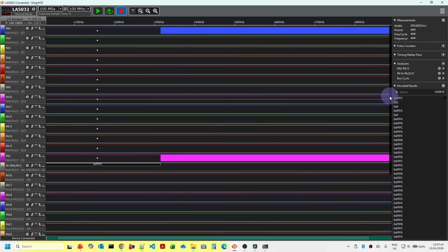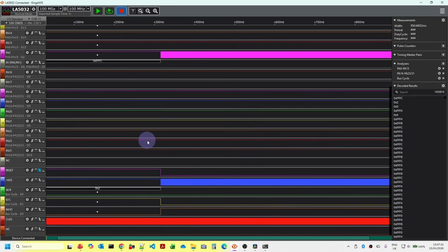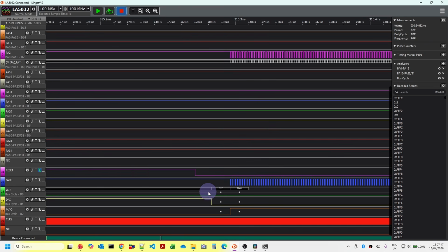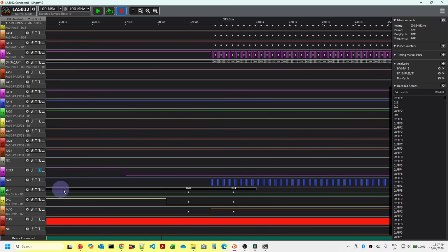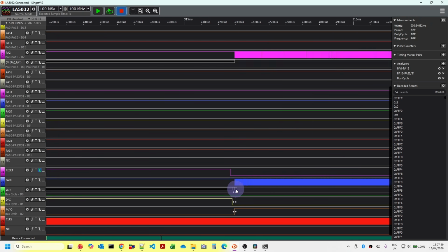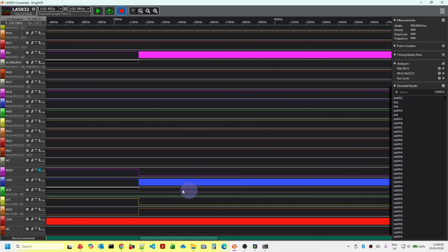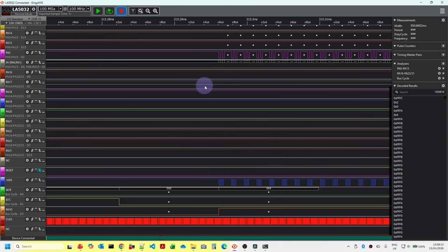And if we just scroll down so we can see some of the other data, we can see that just as it comes out of reset, we had the status there of 0, which was interrupt acknowledge, and then we've actually got 04. And in fact, the status here of 04, which is read instruction, if we look at the control lines, the write read, the data control, and the memory I/O, you can see these haven't changed at all. So basically the rest of the data here is always going to be reading code.